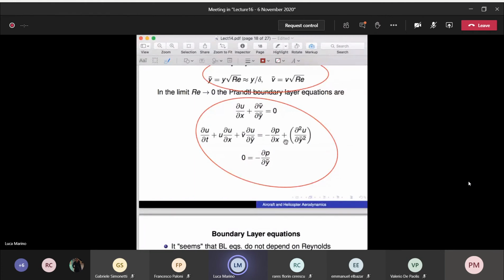You have to solve the Euler equation, so you find the solution around the wing without viscosity. Okay, then you can introduce the boundary layer, and what you are going to change is that instead of having the impermeability condition, you will have the adherence condition, the no-slip condition at the wall, and what is going to happen is that you are enlarging the region very close to the body to expand it and to see the effect of the viscosity.